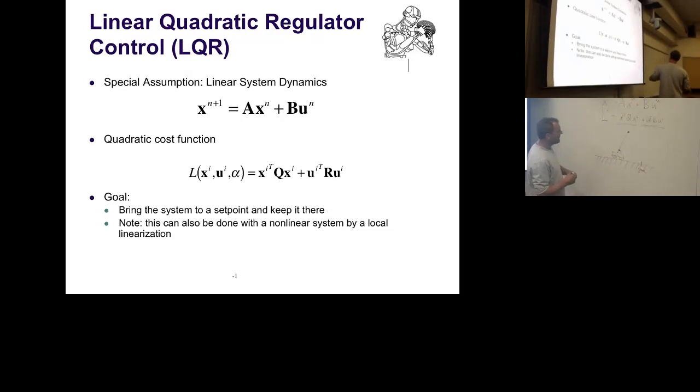Now, if you have a problem like this, then the easiest way is to basically define x relative to the goal. You basically say my x is relative to the goal, so I call this x, which is essentially my current state minus the goal. So it's a redefinition. And what I want to do is regulate the state x to become 0, and I want to use as small motor commands as possible in order to get there.